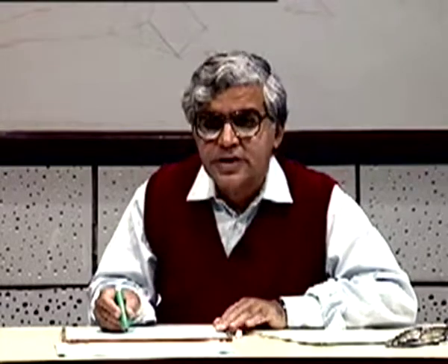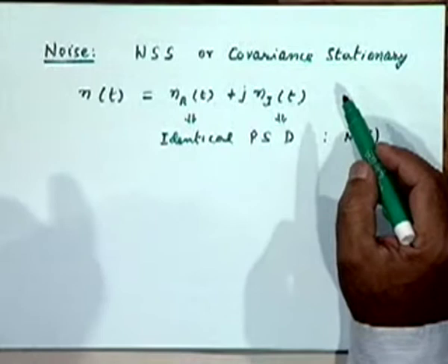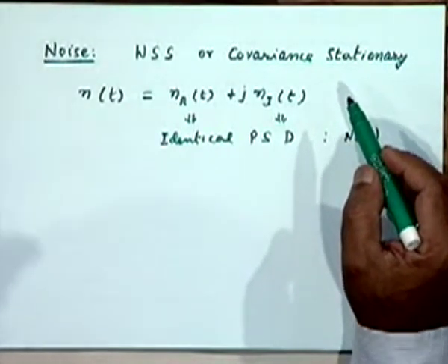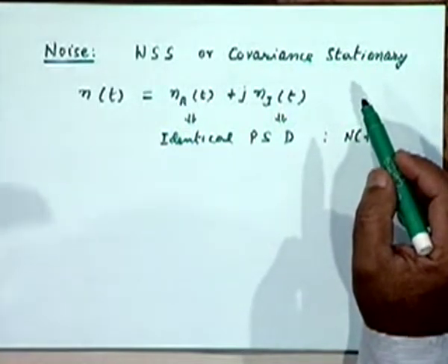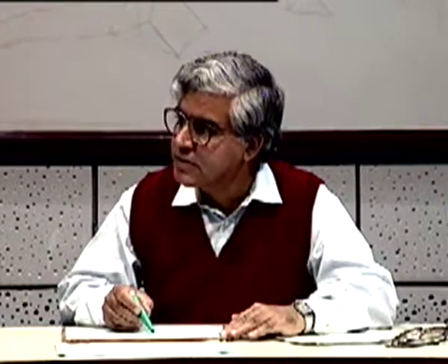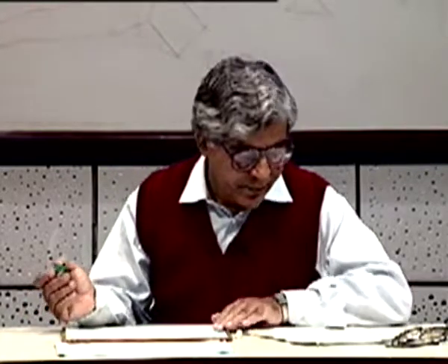For example, you must keep in mind the physical picture behind each of these complex signals. These are the kind of things that you might see on the quadrature channels after you have done, let us say, down conversion of the incoming passband signal into a baseband representation, which would be a quadrature signal and may contain the in-phase noise and the quadrature phase noise. And typically they will have identical power spectral characteristics.